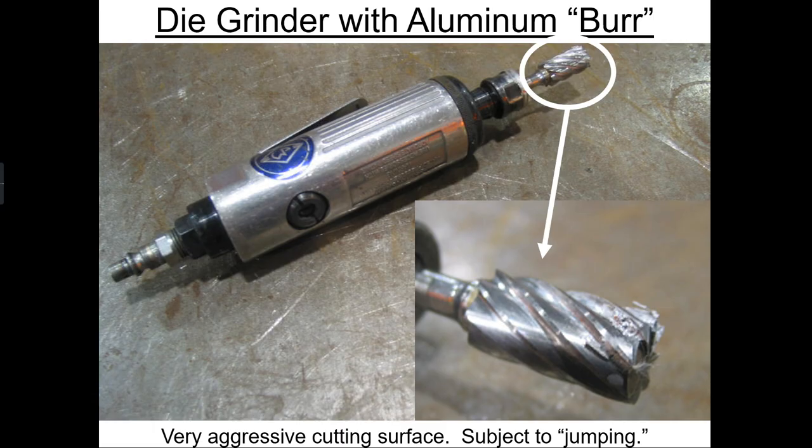There is going to be a rule for almost any aluminum that's going to get welded, and that is no abrasives. I don't care if it says that it's made for welding or for grinding aluminum or not. It's not made for welding aluminum. It's only made for grinding aluminum. They don't make a carbide related disc that has anything to do with removing material in the weld zone.